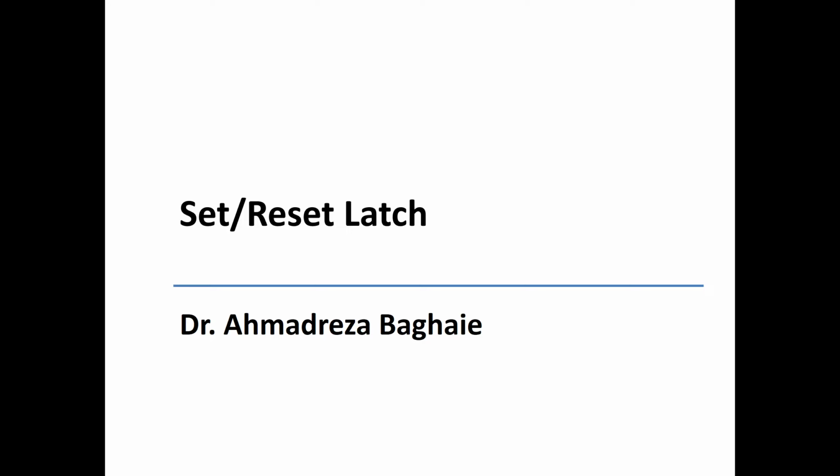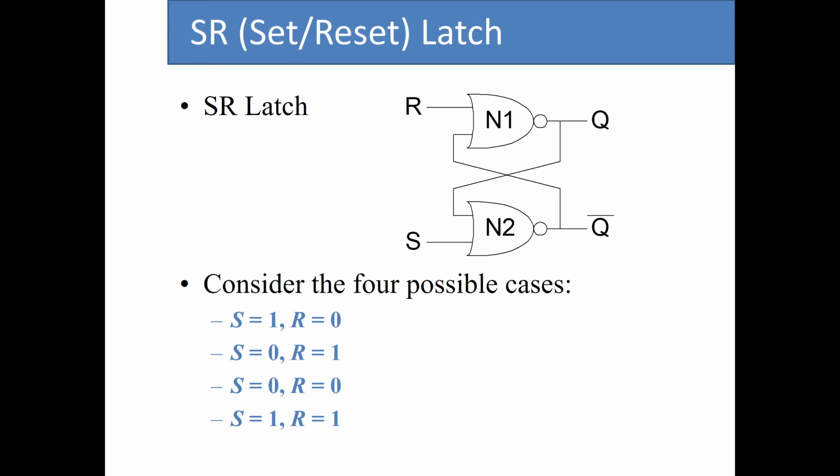In this video, I want to talk about the SR-Latch, or set-reset latch. You remember from the previous video that we were able to use two inverters to create a bistable circuit. Even though it had the memory capability to store 1 bit of information, it was not that useful because we didn't have any input to control the value being stored in the bistable circuit.